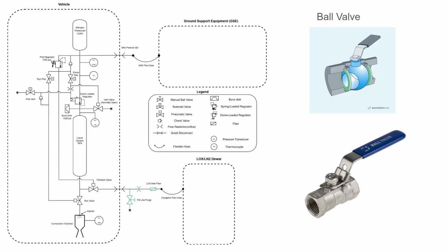The reason this is necessary is because again, liquid oxygen is cryogenic, and if kind of left on its own in a pressurized container, it will continuously heat up, continuously increase the pressure until something breaks, essentially, usually in a catastrophic way. So this ball valve is connected to the fill line, and this allows us so that once we're done filling the tank, we will close the dewar.